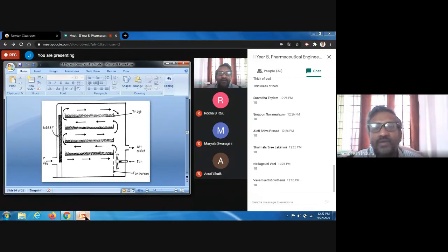What do you require to do? You need to tell them scientifically what you are keeping constant and what you are varying. Now it is the thickness of the bed, making it a constant. Once you make it constant, if your batch size is fixed, it is also fixed. If it is 50 kilo, you can take 10 trays, suitable to accommodate that particular batch. In this case, you are taking 10 trays, each accommodating 5 kilo, and the total batch size is 50 kg.